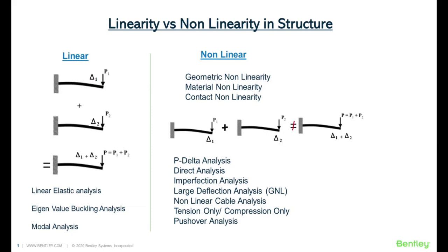Now, when is it okay to use the load combination? That's very important. The load combination is only allowed if your structure is behaving linearly. Now, what is the linear combination? Linear combination is something like superposition. Most of the cases for linear elastic analysis behave as a linear analysis.